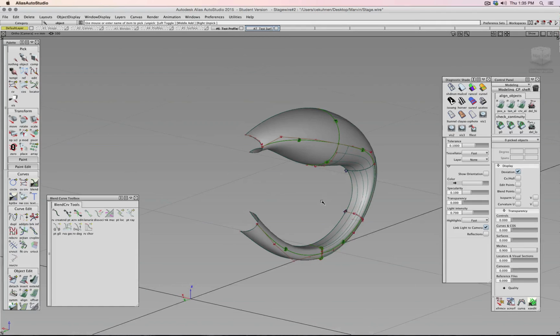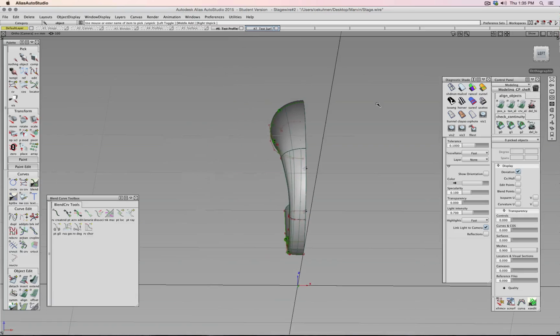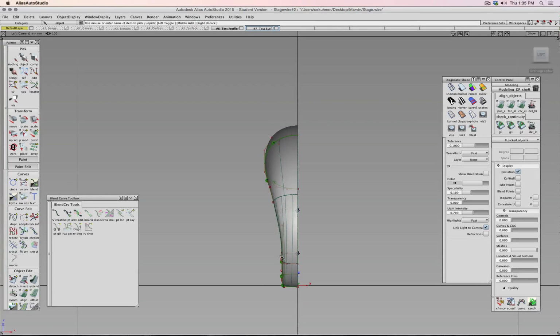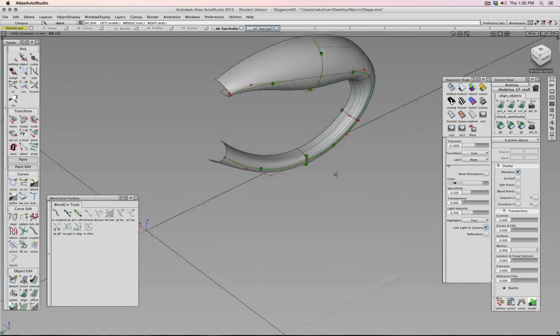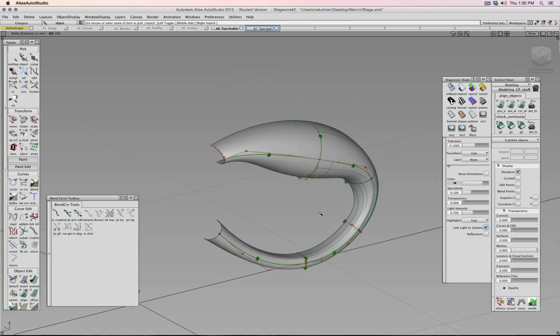But I hope that you started understanding the process of first the boundary outsides and maybe some cross sections, and then at one point I needed to pay attention to the midlines, and everything needed to be cut apart. And that's a very typical aspect in Alias, that you build everything out of four-sided patches, which honestly is pretty standard for NURBS anyway, but specifically the way the tools are built in Alias, it forces you to follow that methodology, and it's more work, but you get better results. Okay, so then in the next video let's take a look at the Y shape in the front.